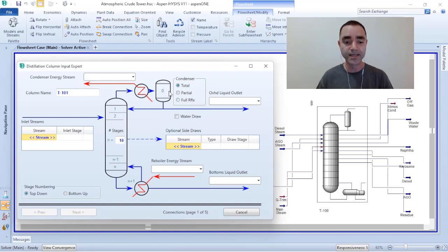And if I keep my distillation column as 18 trays plus 1 reboiler, I will have a total number of stages of equilibrium of 19. And it is below my required total number of stages of equilibrium, that is 20.